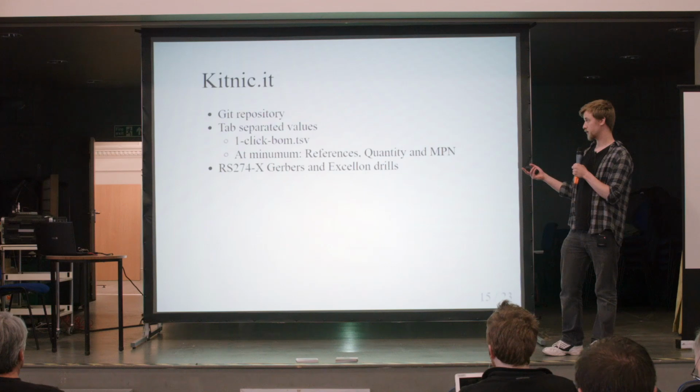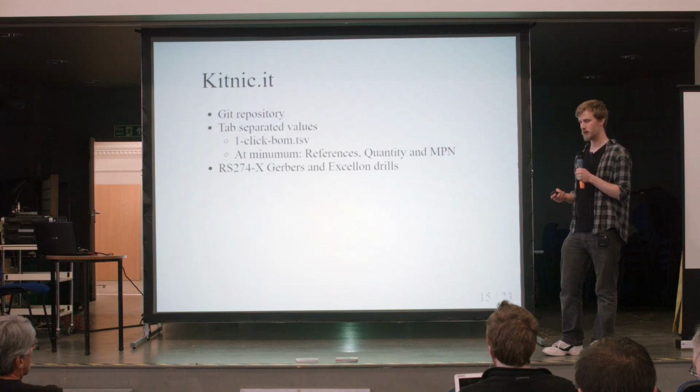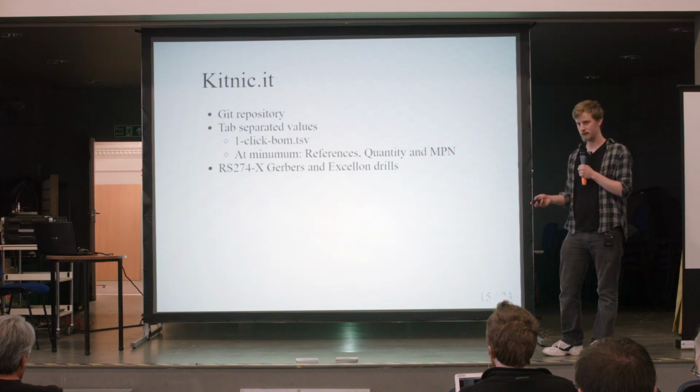And I decided to standardize on RS-274X Gerbers and Excellon drills, because that's what everyone uses to order their boards at the moment. There's newer and possibly better formats out there, but none of the fabs are really using them yet.